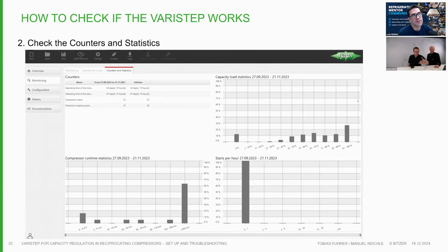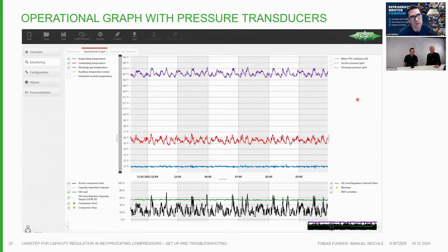I think in the service guide, it says you guys, on average, you want less than 6 starts an hour. Is that right? Yeah. On just your standard compressor. So once again, there's more than one compressor guide to read. They have a lot of different types of compressors. So when you get in there, I've read a lot of them, but you'll read their main guide for their fixed compressors. And then you'll have the capacity control guide for how the capacity control works. Then you'll have the CO2 guide.